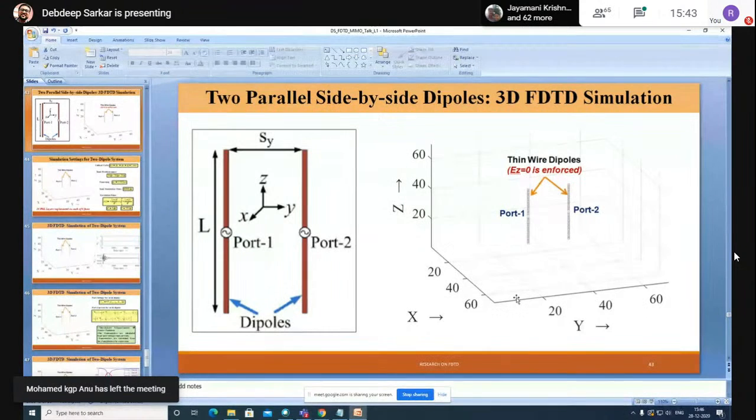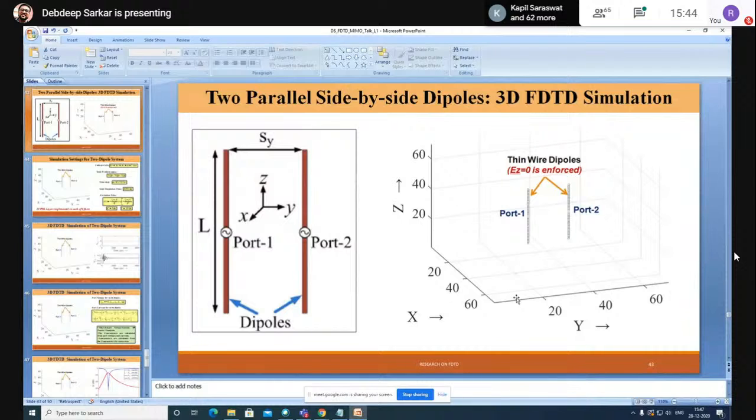In any case, let's say in FEM, when we model it in HFSS, I'm talking about HFSS because most of my antenna design work I did there. Generally, we take a solution frequency and have a sweep around it. If we want to solve for, say, 2.45 gigahertz, we sweep from 1 to 4 gigahertz.